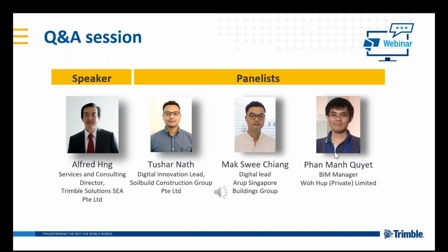I will take up this question. On the limitations of file size or number of elements in IFC, there are a few areas to look into. The first thing is which type of Trimble Connect license you have. For the free version of Trimble Connect, there is a limit on the file size.